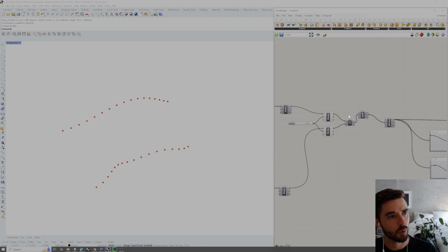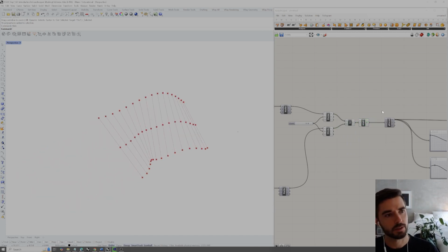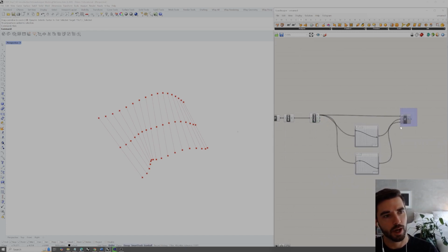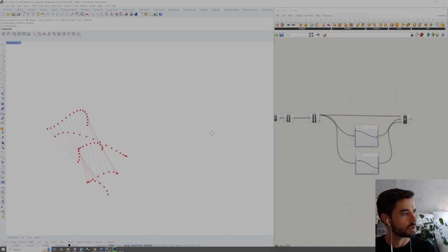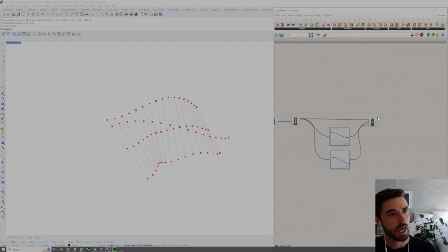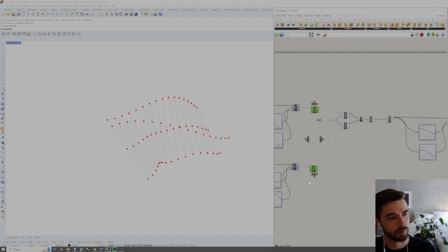and we're taking those points, we're drawing lines between them, we're then constructing a midpoint between those lines, we're then deconstructing that midpoint and using a graph mapper to rebuild that midpoint into an adjusted version of itself. So we now have this other new set of points there, and what we did in the last video is we also drew a third curve through these sets of points, just like we did with these NURBS curves before it.